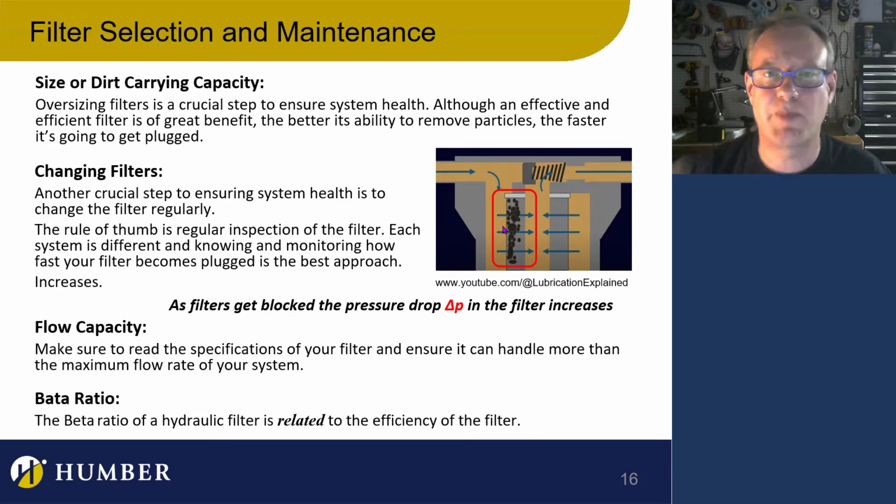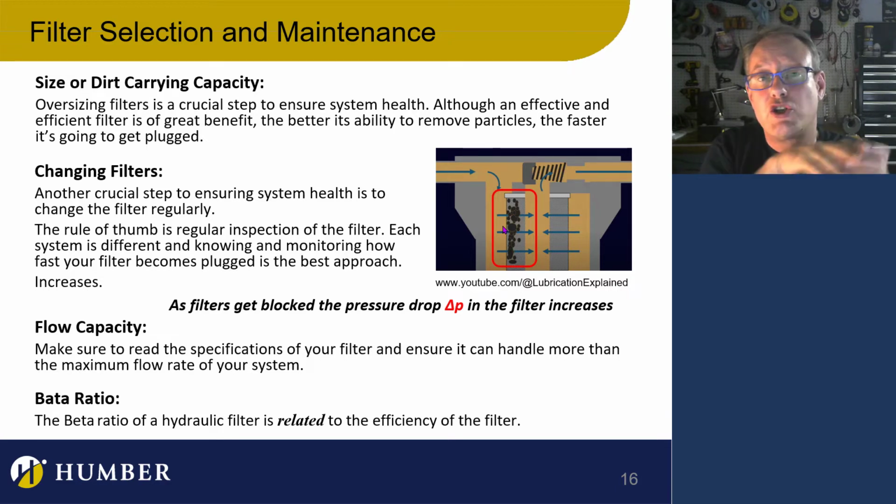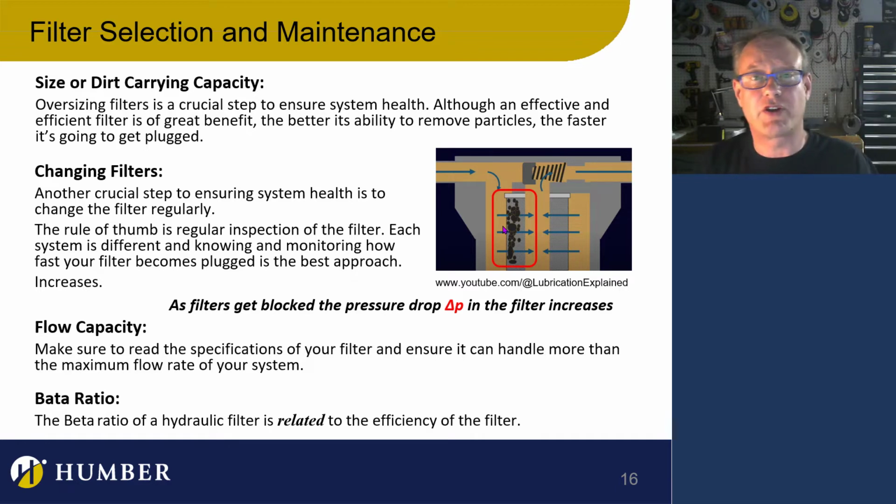It's brand new. You just put it in. There's going to be a delta P. There's going to be a pressure loss through that filter. Work has to be done to put the fluid through the filter, and work and energy are the same thing. So if I'm losing energy, that's going to be seen in the pressure.